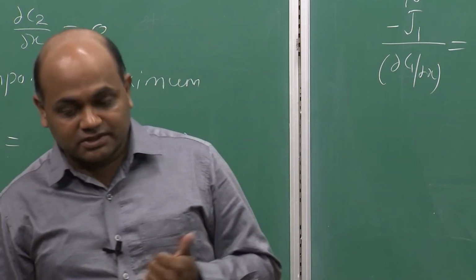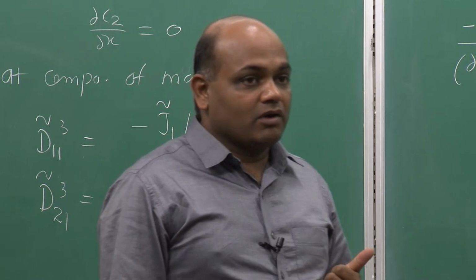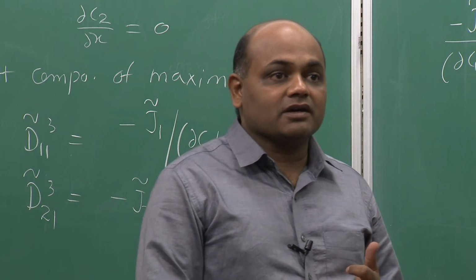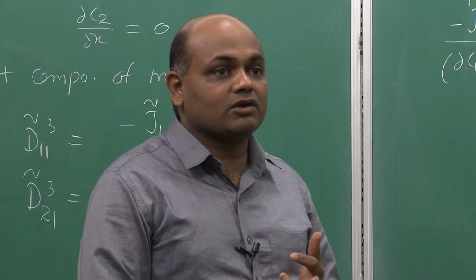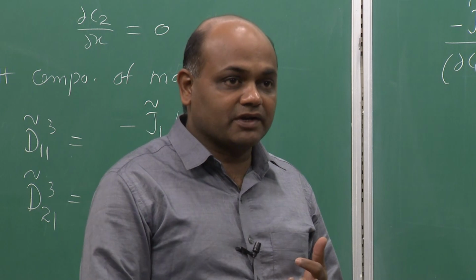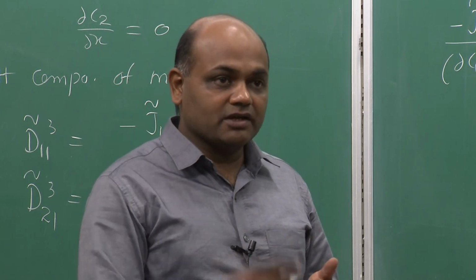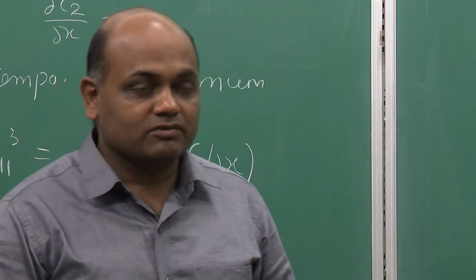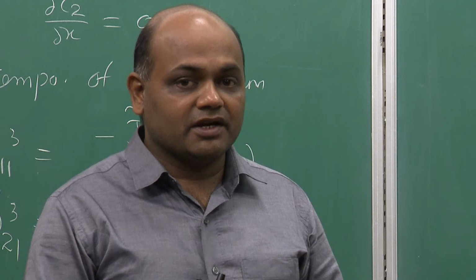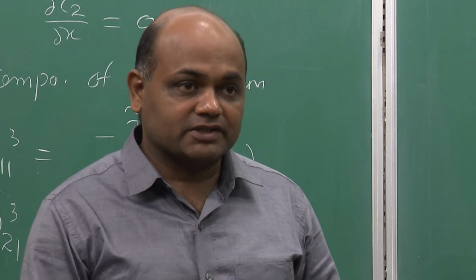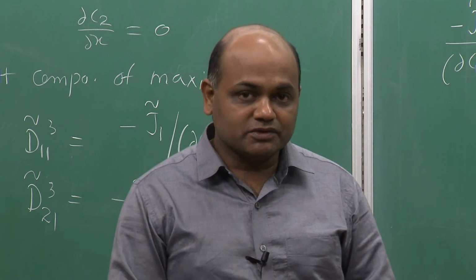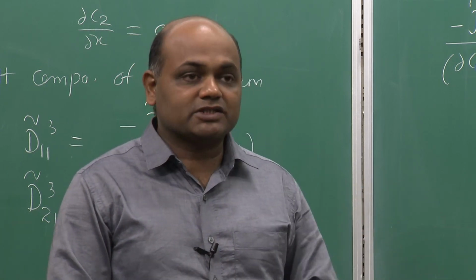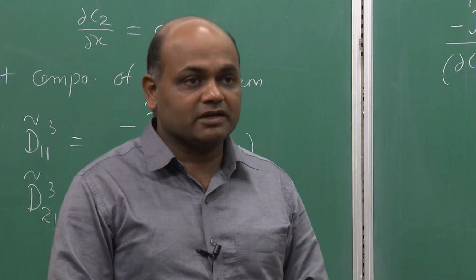Again, one assumption there will be all the components which are supposed to be invariant will not develop any uphill diffusion region, which means they will not exhibit significant diffusional interactions from the other components. Okay. So, these are some of the experimental techniques which we can use for determination of interdiffusion coefficients in multi-component systems. In the next class, I will show you some specific examples from the literature in which such estimation of interdiffusion coefficients has been reported.